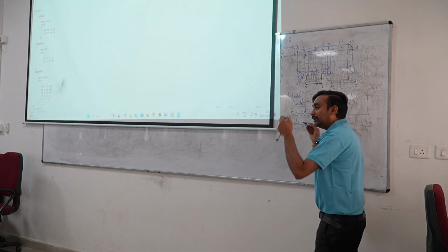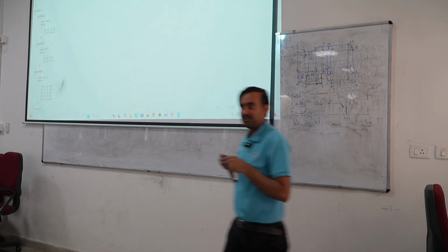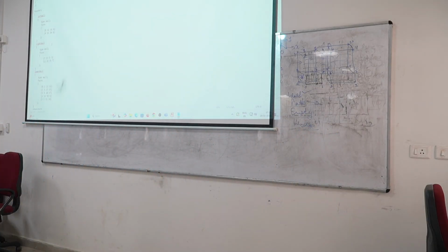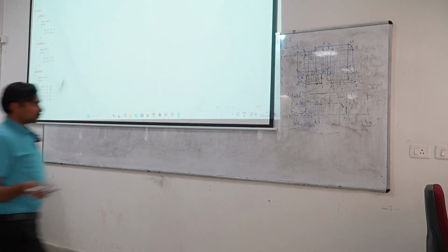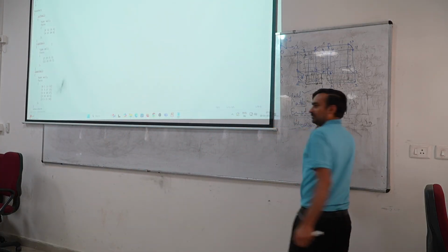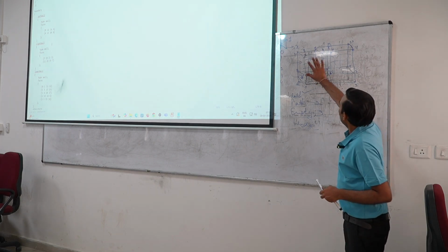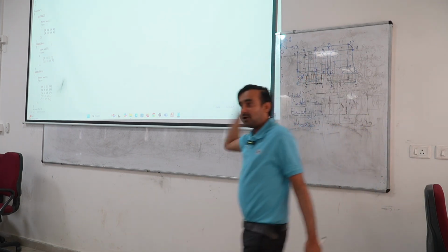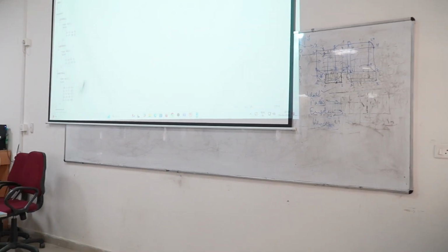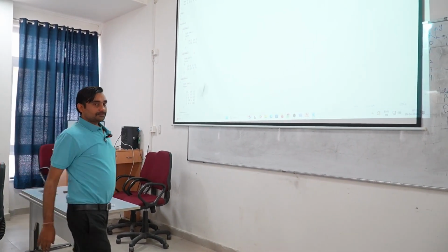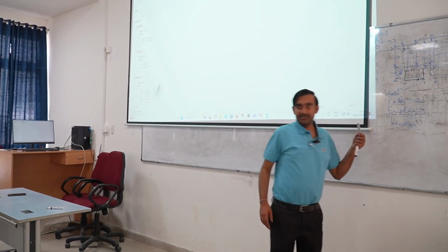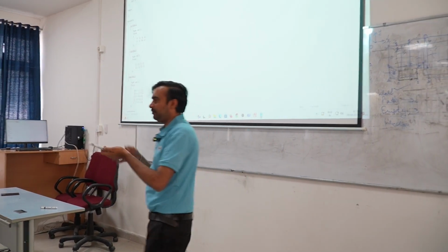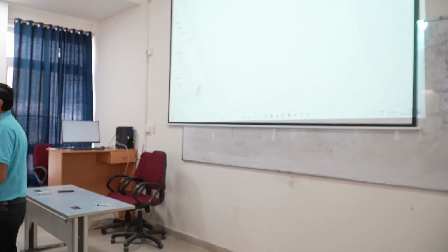If you are doing a two-dimensional simulation, there will be some boundaries along which I am not solving the flow. These particular boundaries I need to specify as type empty. For example, all the front and back boundaries for this simulation we need to specify as empty. Then, other than this, wedge we will be specifying when we talk about axisymmetric simulations.